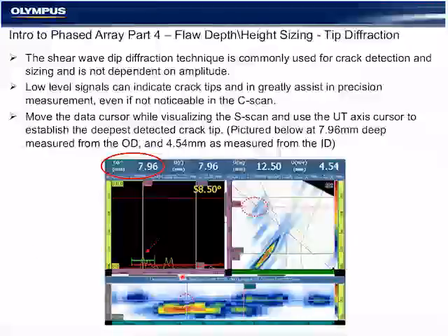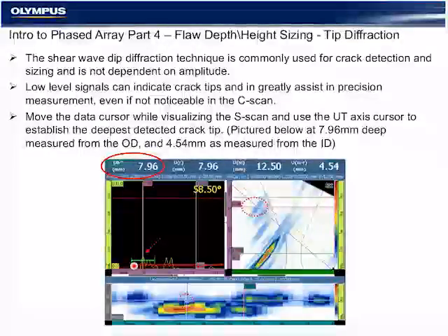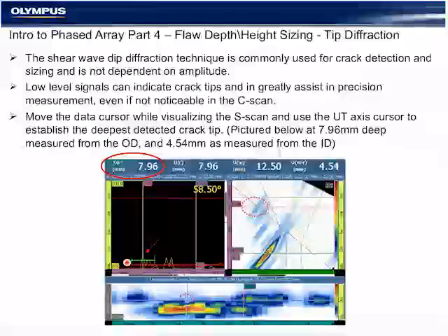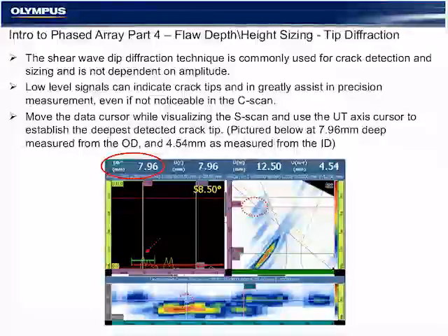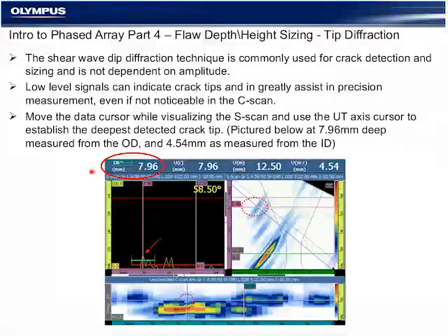We will also use gate data for the depth reading. So for the DA reading, it's going to take the gate information, it's going to take the max peak within the gate, and in this case, we're looking at the DB reading, which is associated with gate B, green. There's another reading, DA, associated with the red A gate.